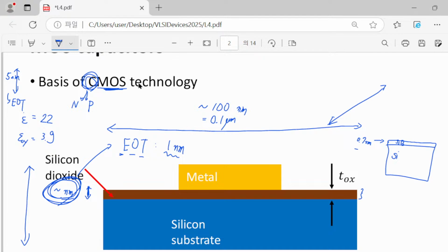So this is really unavoidable. After that, you can add hafnium oxide, and its thickness can be controlled in the fabrication line, quite easily, like 2 nanometers or even thicker. If you have, for example, 2 nanometers, maybe it's okay. Your overall EOT can be maintained below 1 nanometer.